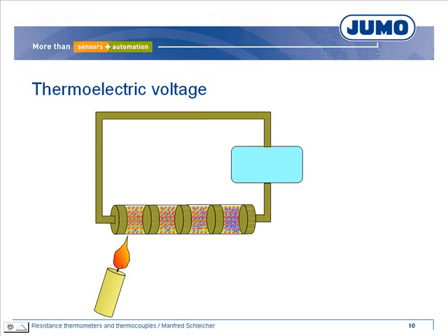By connecting the cold and the warm wire end to the device, you can try to measure the resulting voltage. The measured voltage is 0 mV. The reason is the same effect in the measurement connection. Due to the difference in temperature, the same voltage arises.